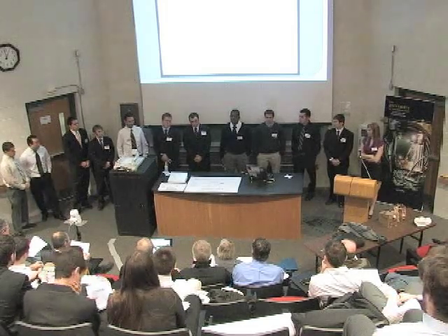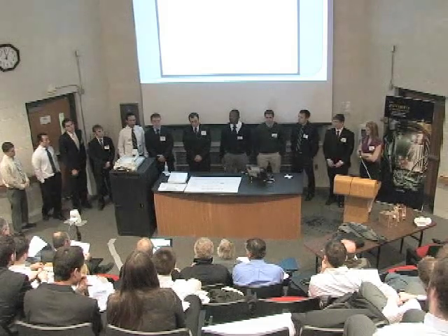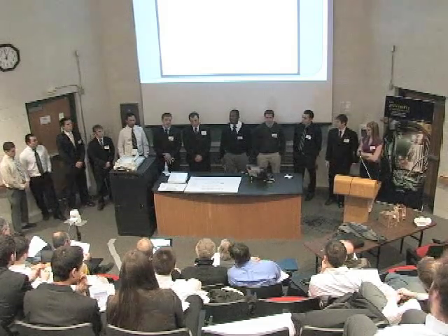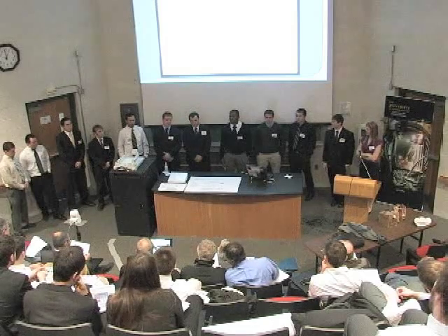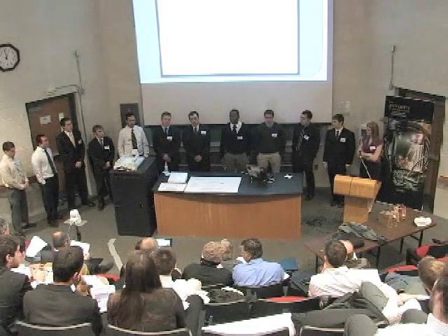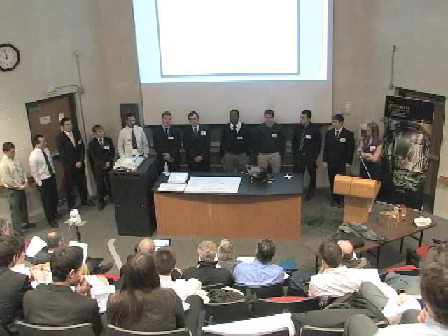If we were given further exploration of the site, we suggest test piles around our actual buildings just to prove that the fill is consistent. But for now, we're going to assume that it's consistent in our restaurant and parking garage. So it looks like your piles then will be fairly short. Yeah, we'll be going down about how many feet? About 10 feet, I would say. Yeah. Really short piles.